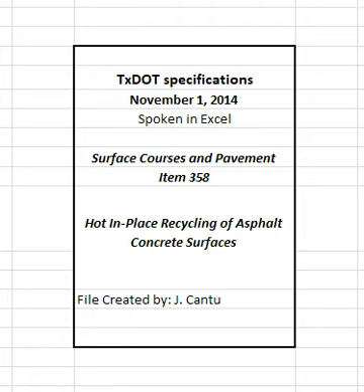3.1.3 Recycling Agent Application System. Provide a system for adding and uniformly applying a recycling agent at the specified rate to the hot, loosened material. Control the system to within 5% of the target application rate. Equip the recycling agent system with positive on/off capabilities to prevent any dripping. Add the recycling agent during or after milling has taken place to provide uniform application of the recycling agent and adequate mixing with the recycled material during the mixing cycle.